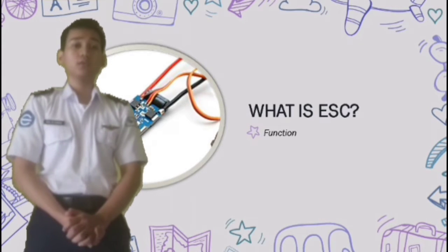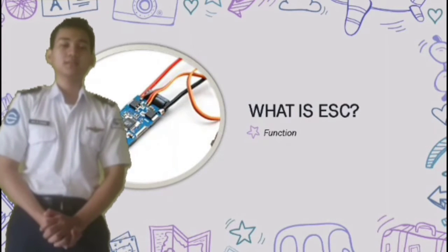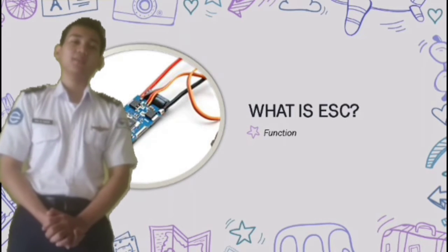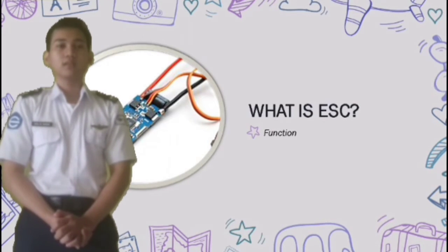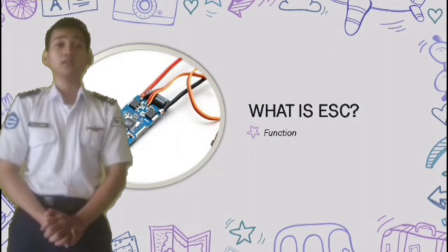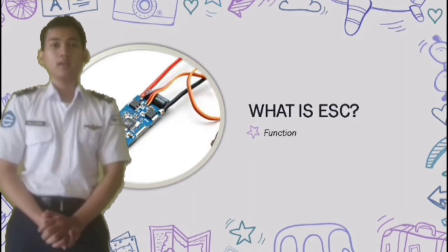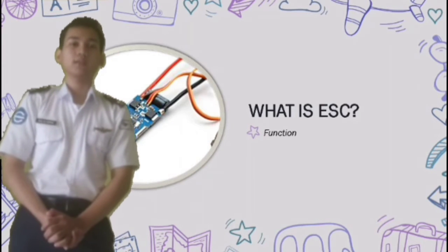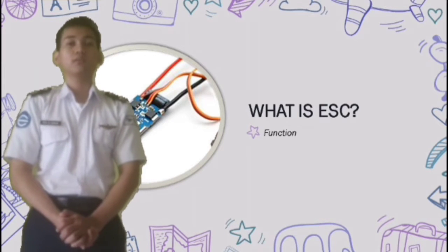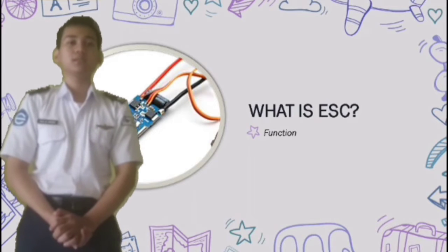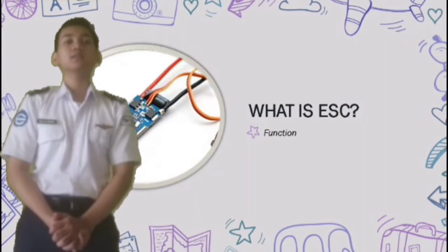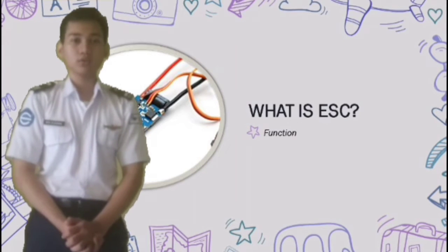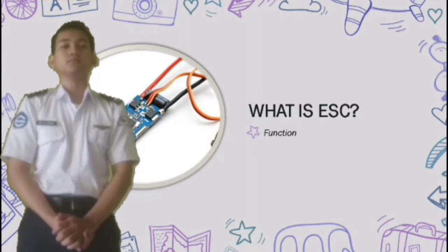Electronic speed control follows the speed reference signal derived from the throttle lever, joystick, or other manual input, and varies the switching rate of the field effect transistor, or FET network. By adjusting the work cycle or switching frequency to the transistor, the motor speed is changed.